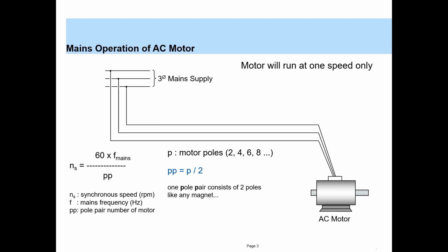Let's say your pump application demands only 800 rpm. In this case, you are wasting the rest of the rpm. You will be operating the motor at 1500 rpm, but your requirement can be sufficed at only 800 rpm. And also you are extracting extra energy or power, because your motor will need more power to run at 1500 rpm. So if you are somehow able to run the motor at 800 rpm, this motor will consume less energy, right? And this will result in power savings and operating cost savings as well.